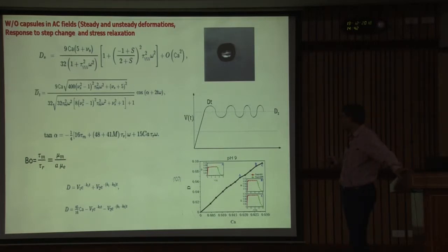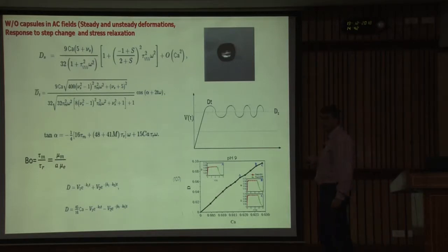Whereas in the electrohydrodynamic method, one has access to a wide range of frequencies, and one can then estimate the loss and storage moduli as a function of frequency all the way up to hundreds of hertz. There are applications, at least in petroleum refining, where interfacial rheometry is required at very high frequencies, but there are no instruments as of now to do that. So this is still a dream.